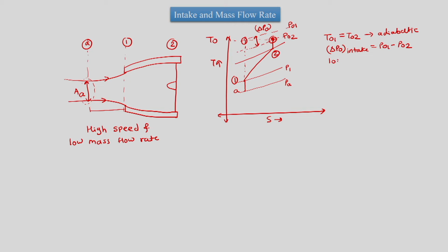So, there is loss in total pressure in the intake, and this rise in pressure from A to 1 is external compression, and this 1 to 2 is internal compression.